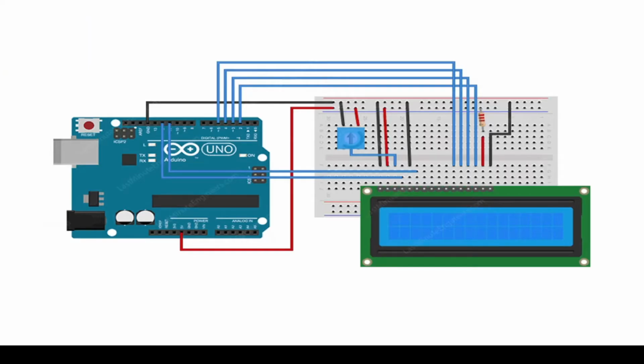Okay, as we have tested our LCD, the LCD brightness is varying very properly with the variation in the knob. So my LCD is perfect now because I can vary the brightness very properly by varying the knob, right? So now let us try to display some words on my LCD so that our interfacing part will be fulfilled, right? So as I explained to you, we have pins 7 to 14. The complete 8 pins will be used for displaying the data on the LCD, right?